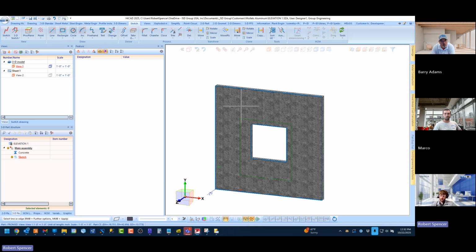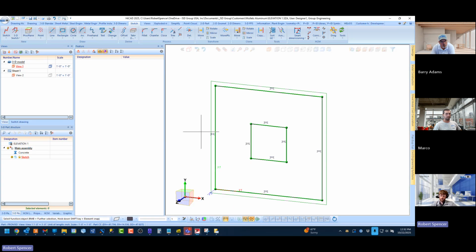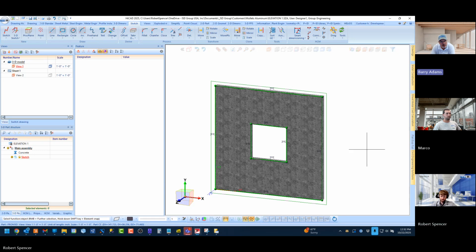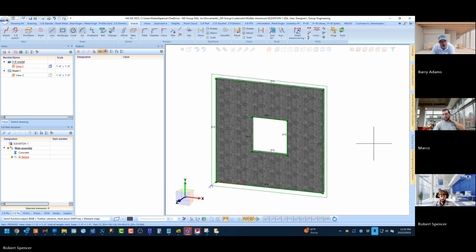And I click once and they turn teal. Once they turn teal, you do a middle mouse and I just took over all the edges of that surface. You just created sketch entities based off of edges on the surface you clicked on. Correct.